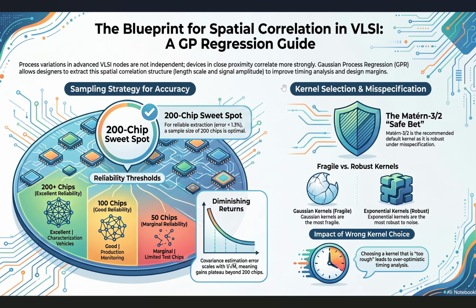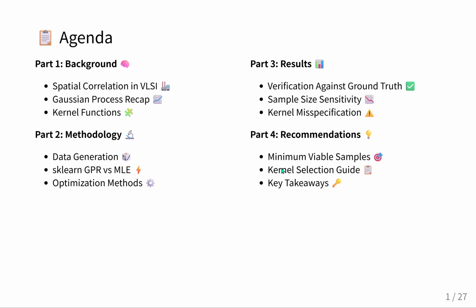That's a great analogy. And understanding why that cookie sheet effect matters is basically the difference between a chip that works and one that completely fails. Wait, really? It's that drastic? Oh, yeah. If engineers just assume every component on a wafer acts randomly and completely independently, they're designing for a fantasy world. They miss the reality of that spatial correlation across the wafer.